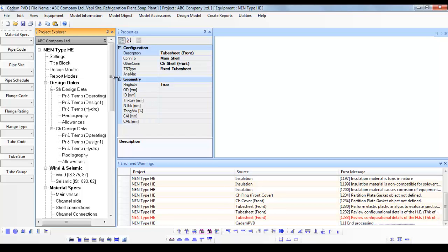First, increase the tube sheet thickness. Second, increase the integral shell and/or channel thickness. It is permitted to increase the thickness adjacent to the tube sheet only. Third, perform the elastic-plastic calculation procedure as defined in UHX-13.7.